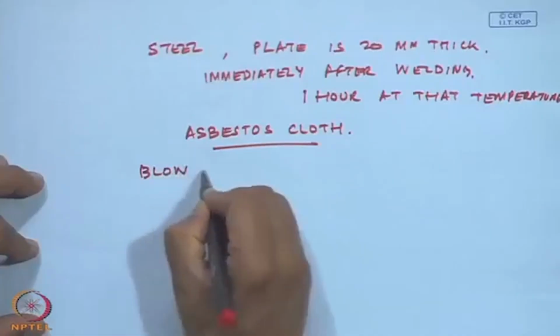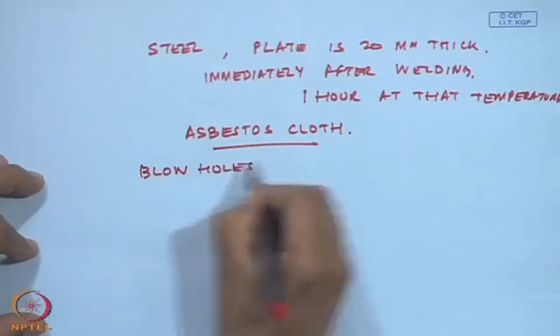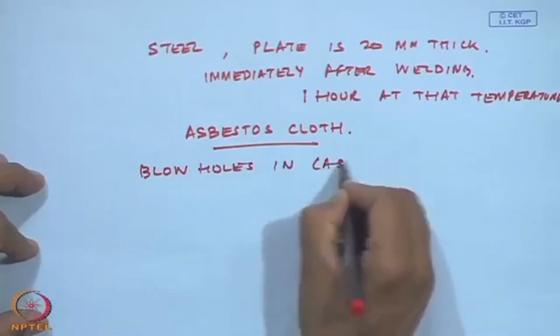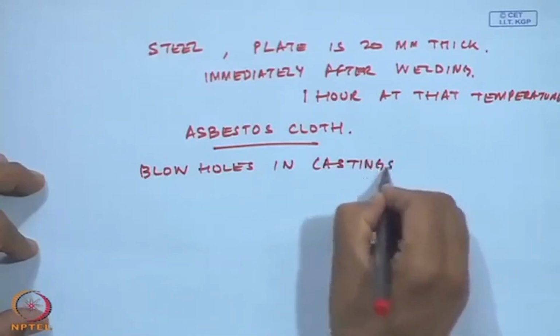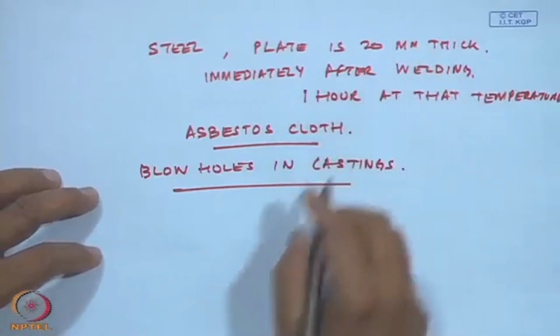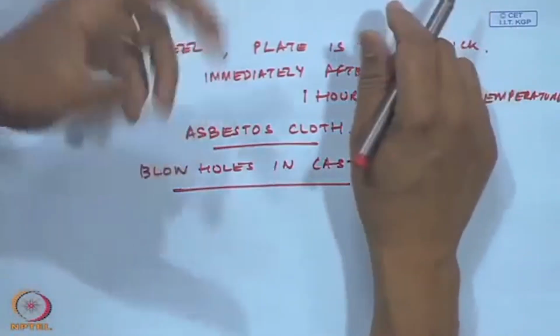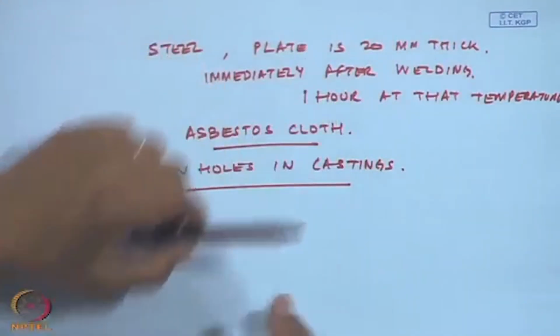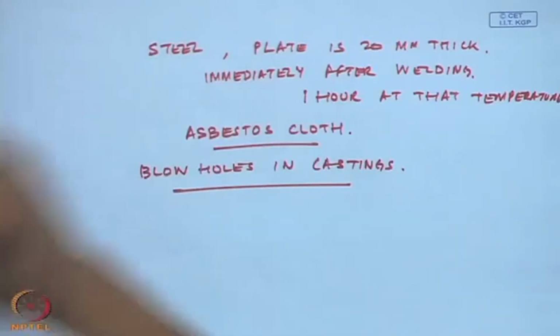Okay. Another reason, of course, the cracks occur is because of casting defects, blowholes in castings which go undetected, poor casting, and then of course, these blowholes etc. can be checked by ultrasonic testing. Okay.